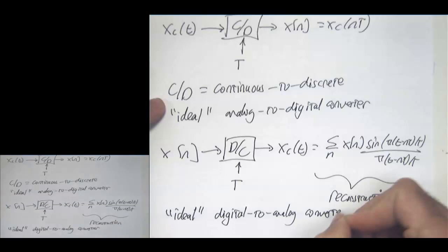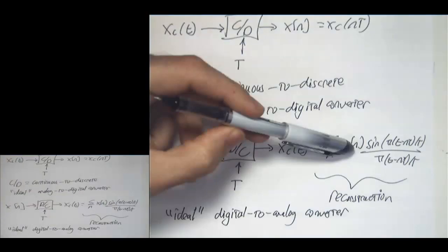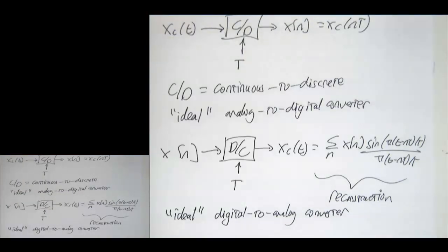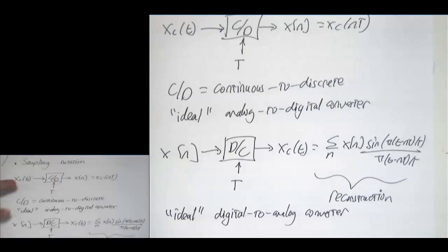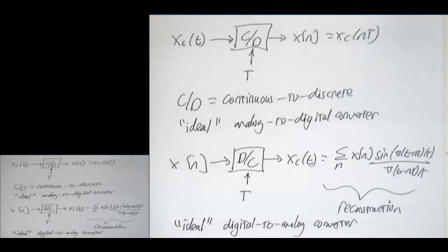And so again, we don't have the quantization effects. A lot of times also, digital to analog converters don't do a very good job of implementing the sinc function. They might just have a rectangle, for example. And then you need subsequent filtering to fix that up, or you could do it digitally. But anyways, for the development in the class and also in the labs, it's sufficient to use the ideal forms of those converters. So any questions about that? I think I got it correct this time.